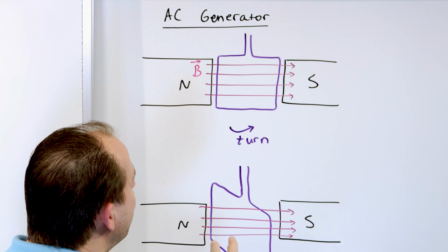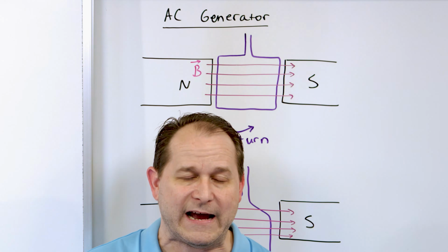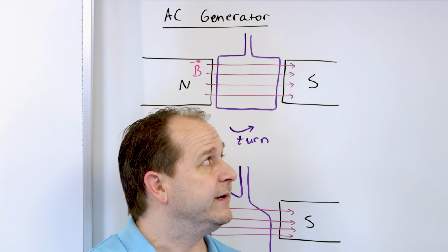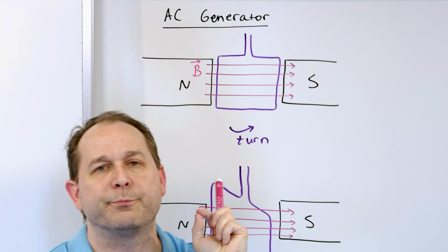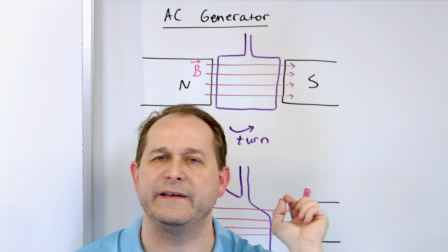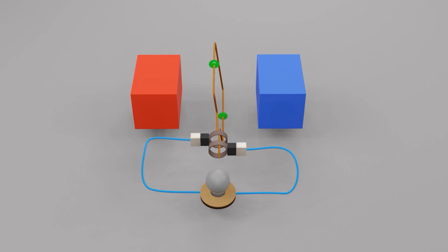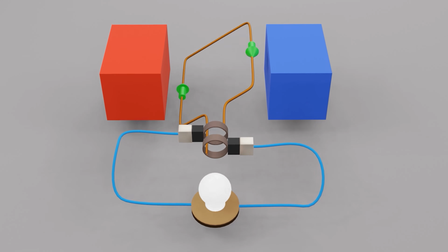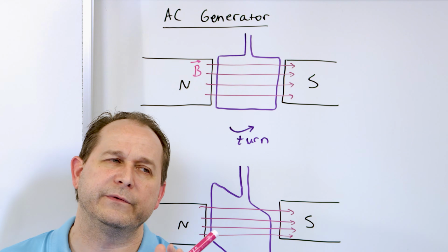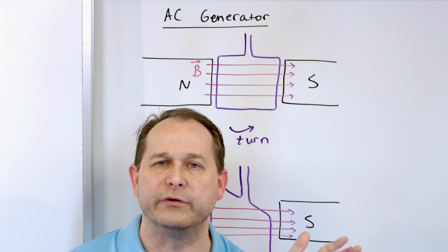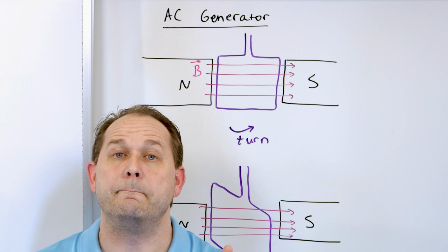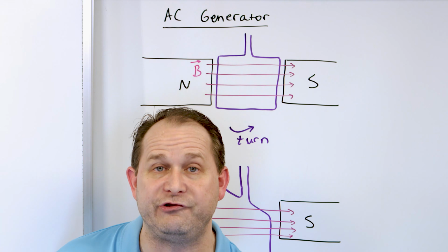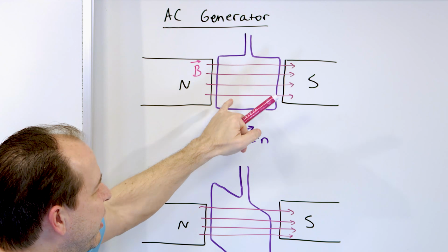But basically, when you turn this thing, it turns out, no pun intended, that a voltage is generated across the terminals here, which is proportional to how much of this magnetic field cuts through and changes with time, cutting through this loop of wire, cutting through the cross-sectional area. So it's not generating voltage based on how much field is flowing through the loop. It's generating a voltage based on how much magnetic field lines are changing that are cutting through there. Changing is a better word.